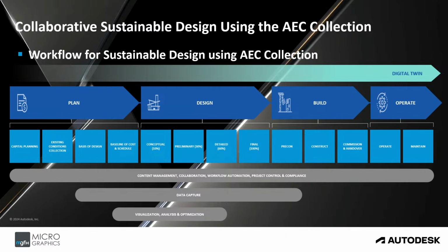During your planning stage, starting with the pre-conceptual design or early design and massing with Autodesk Forma. The journey begins with Autodesk Forma, where conceptual massing models are created. This phase includes exploring building forms, testing site conditions, and evaluating initial design feasibility. The key features would be massing tools, environmental analyses, and early-stage data visualization. The outcome: a conceptual massing model to guide further design stages.